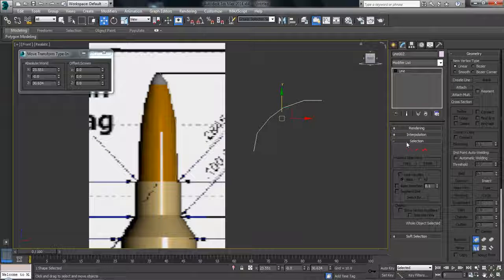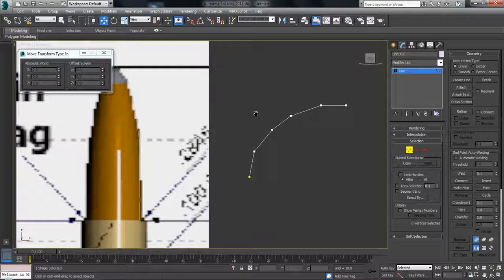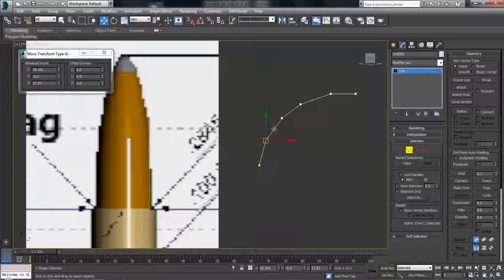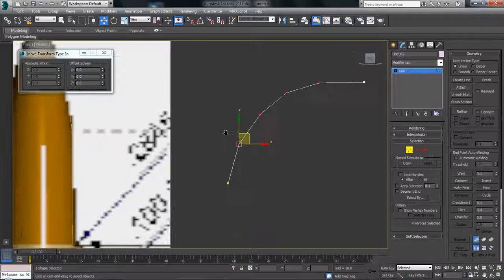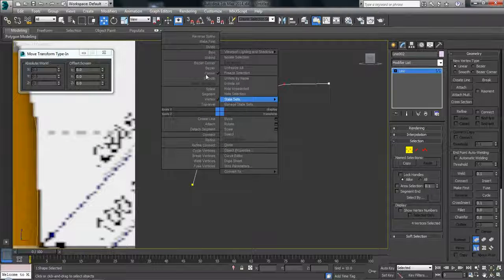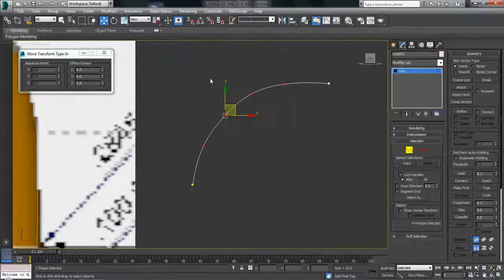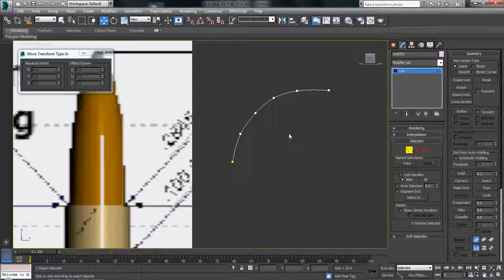So I'll just go to the modify panel and into Vertex. Now, if we wanted to build a smooth curve here, we could sit here all bloody night and move these until we get the proper curve. We could even come in and switch them away from this angular type of point called a corner to smooth. And that's a bug that annoys me sometimes. It won't select the right quad menu. So I'm just going to change these to smooth. Okay, and that looks like a reasonable curve.